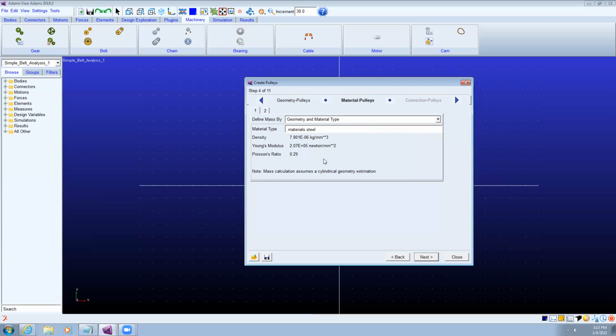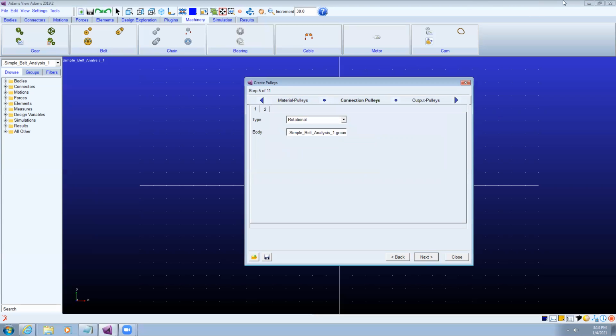Okay, for our information they are shown. We are unable to edit these values. Okay, if you are using any grade of the steel material, then you need to choose add a material, and you just change the values of the density, Young's modulus and Poisson's ratio. Here we say it is the next module.